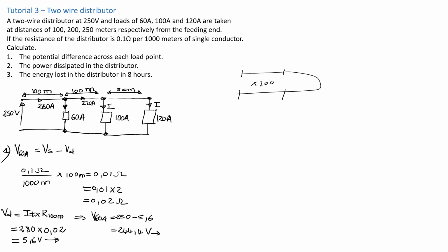Now you understand how I was explaining the scenario of a cell phone. Now there is a drop. Now suddenly this load here is no longer seeing the whole 250 volt. Some voltage is being dropped, which is 5.6. So automatically this load here will definitely also see some decrease from the 244.4. So that is now what we need to calculate.